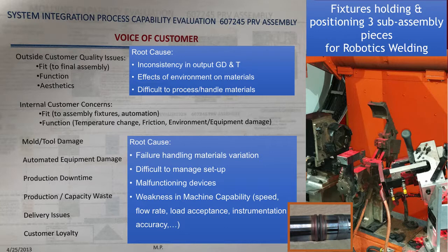The root causes could be failure to handle the material variation, or difficult to manage setups. The setup of the equipment is difficult. Setup people have to do very tight tolerance adjustments without a real good tooling, real good way of measuring and checking and verifying that the setup is okay. Or malfunctioning of devices could be another root cause.